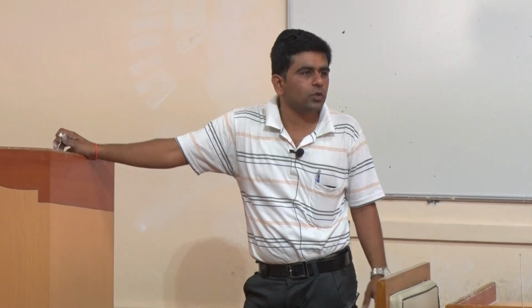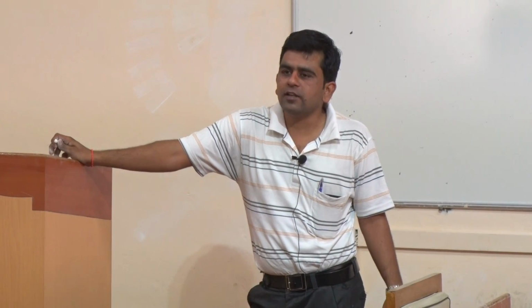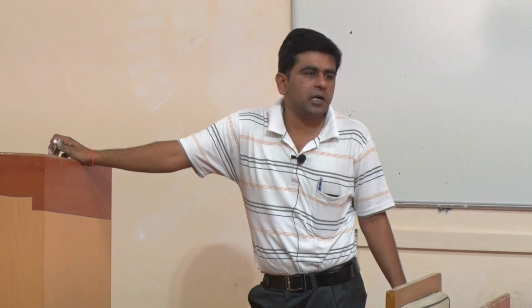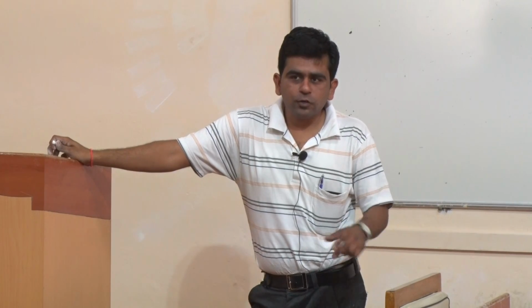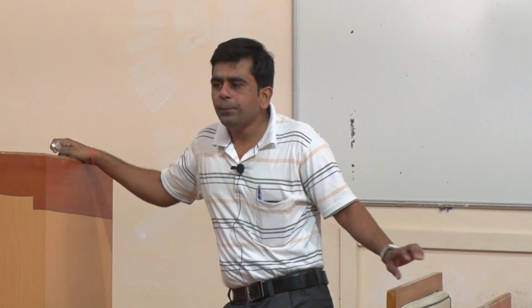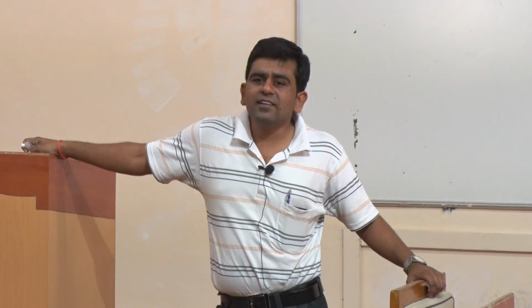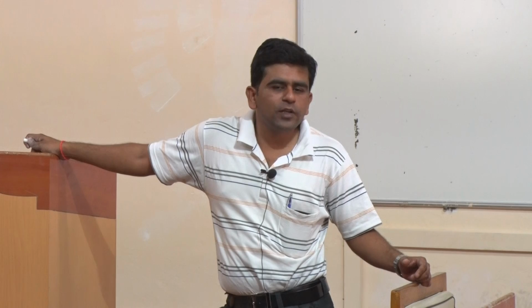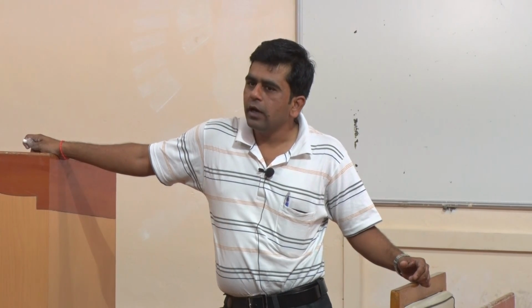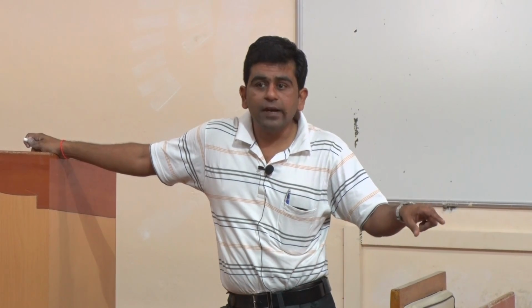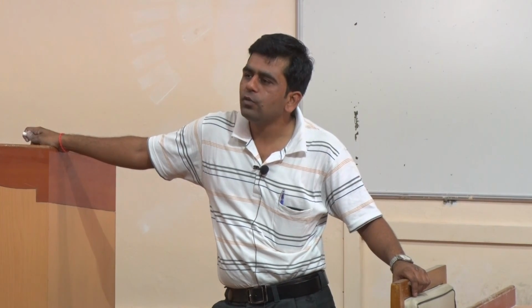So here we get the filter response H(f) in frequency which will give the maximum signal to noise ratio, that is optimum. It should be equal to k times G*(f), the complex conjugate of your input signal, multiplied with e raised to minus j 2 pi f T. In impulse response we can see that h(t) is equal to k, any arbitrary constant, multiplied with g(T minus t). So we have to design such a filter which will give the maximum signal to noise ratio. Its impulse response should be multiplied with your constant k, and it is a delayed version of your input signal g(t).